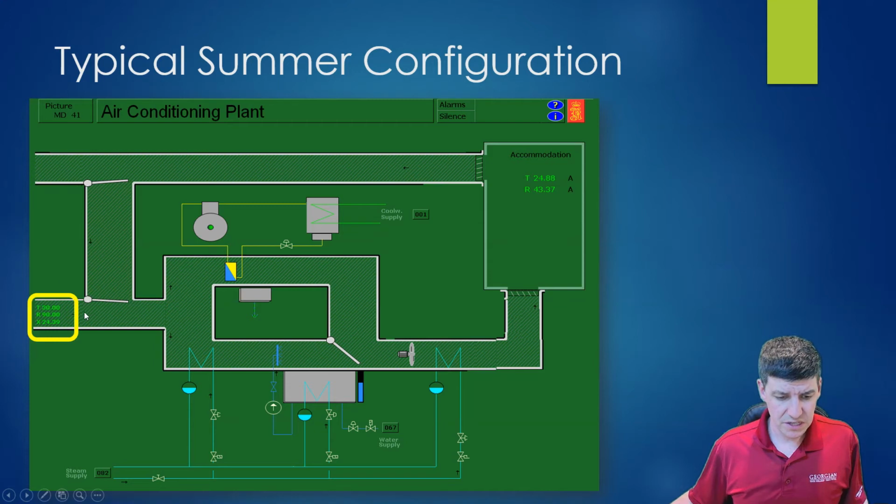So our starting conditions now, we have a little warmer temperature, 30 degrees that we're starting, and it's quite a bit more humid, so 90% humidity. So it has a lot more moisture. Before we were around 0.9, now we've got 24. So that air is carrying a huge amount more moisture with it. So we have hot, humid air that's coming in, typical of a hot, humid summer day in our area.